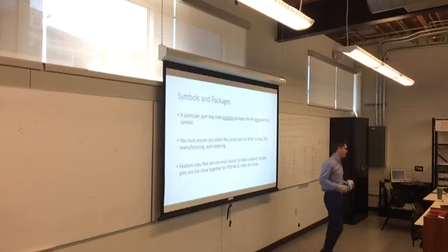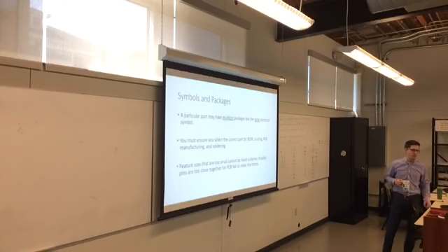Make sure that when you're placing things that it's not too small a package where you physically can't handle it, or you physically can't get the solder between the different pads to make sure that they're connected.